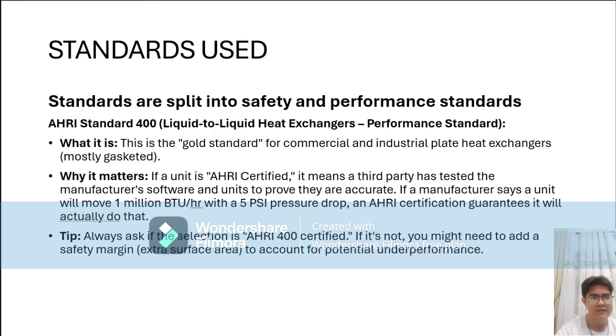Plate heat exchangers also have standards. Standards are generally split into safety and performance standards. ARI standard 400 is a liquid-to-liquid heat exchanger standard meant for performance. What it is: this is the gold standard for commercial and industrial plate heat exchangers, mostly gasketed.